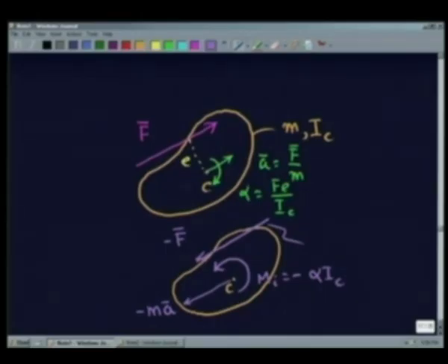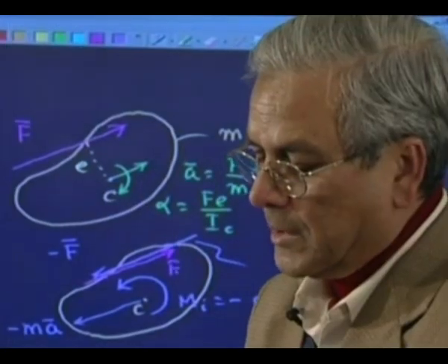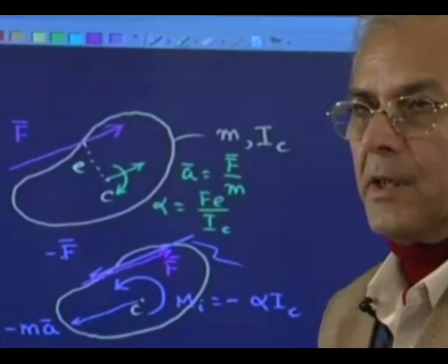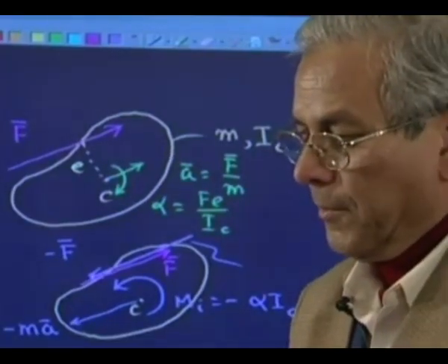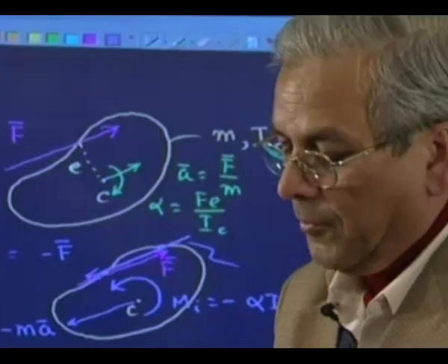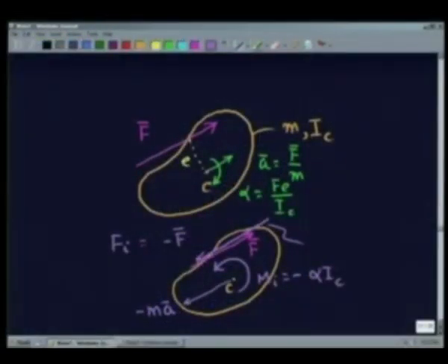Now when this hypothetical force is applied along with the externally applied force F, what is the resultant effect? They cancel each other. This F, which you can also call Fi, the inertia force, cancels the externally applied resultant force, bringing the body into static equilibrium.